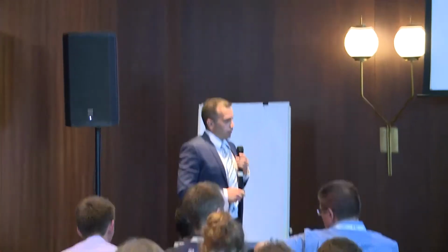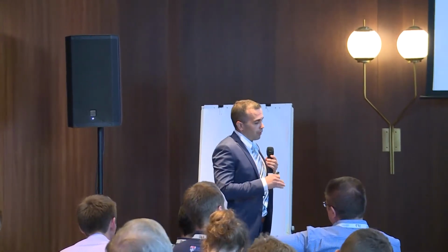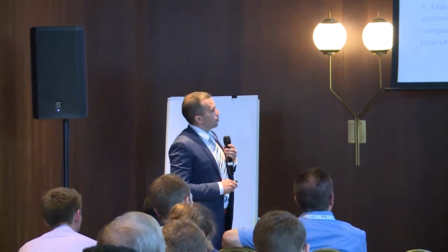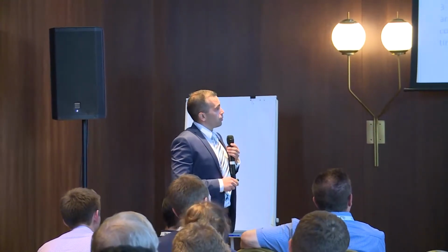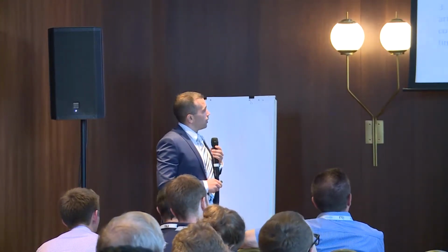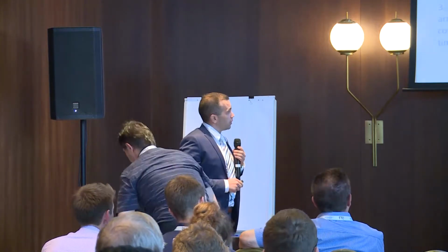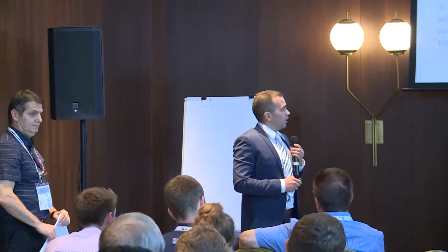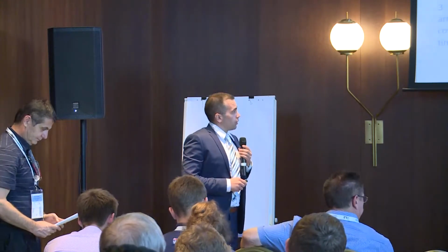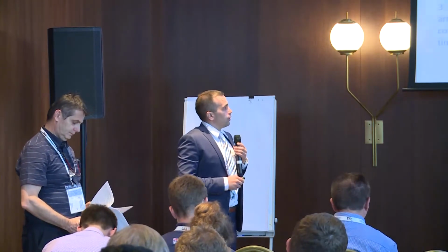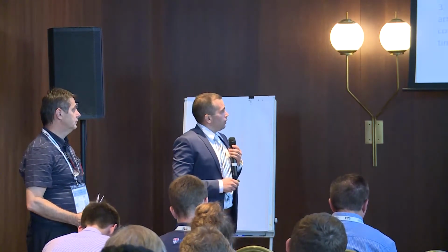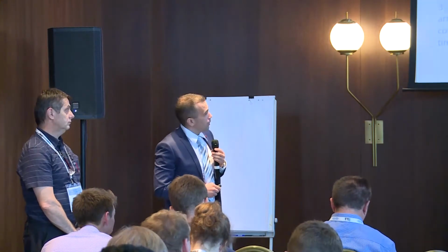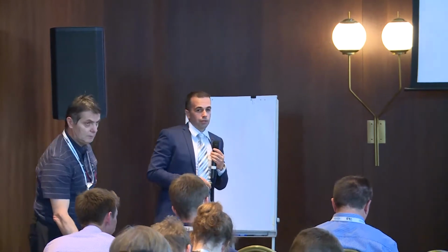Also, for the weld metal zone, we have a significant drop in energy between 20 and minus 40 degrees, especially in crack propagation energy. For fracture toughness, the fracture toughness of the base metal is 86 megapascal, which is usual for a high hardness armor steel. The calculation for the heat affected zone shows triple the fracture toughness of the base metal. The highest fracture toughness is in the weld metal, 4 times higher than the base metal. And thank you for your attention.